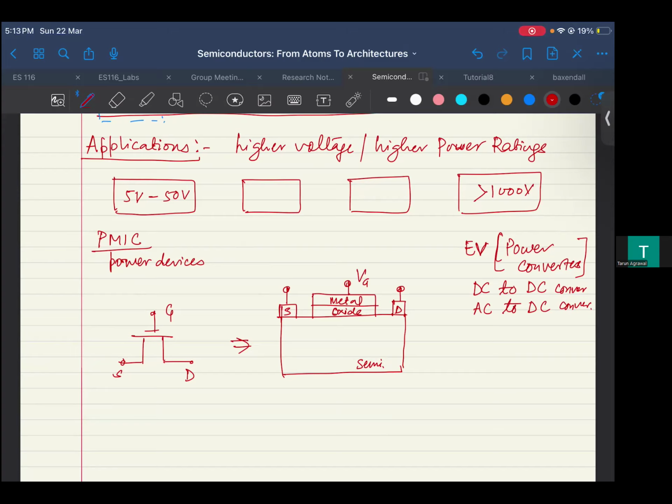We also saw that if we are making a device for electron conduction, we may need some pockets here filled with electron charge, which we can call N charge. N means there are a lot of electrons. Similarly, here there could be a pocket which could mean N. Now, based on the VG, or what voltage we apply, we are able to switch that. That is what we have already seen in one of the videos, how the transistor operates as a switch.